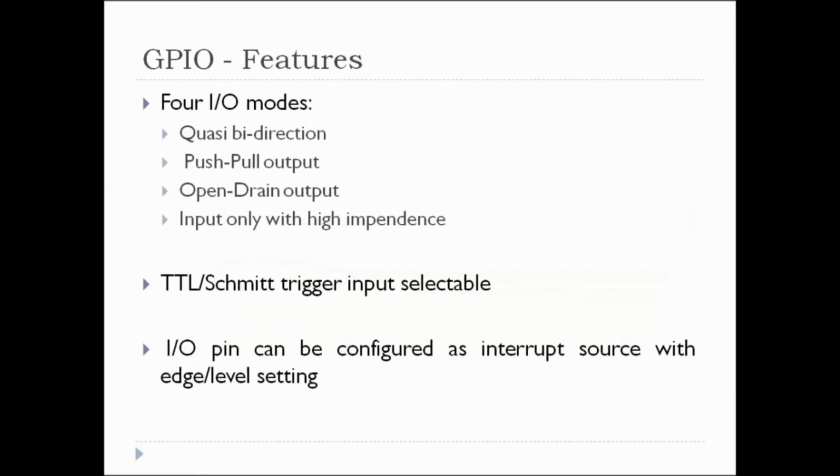It also supports TTL or Schmitt trigger input. The user can select based on the input voltage standard. This IO pin can be configured as an interrupt source with edge or level setting. So we can trigger an input interrupt either on edge or level.